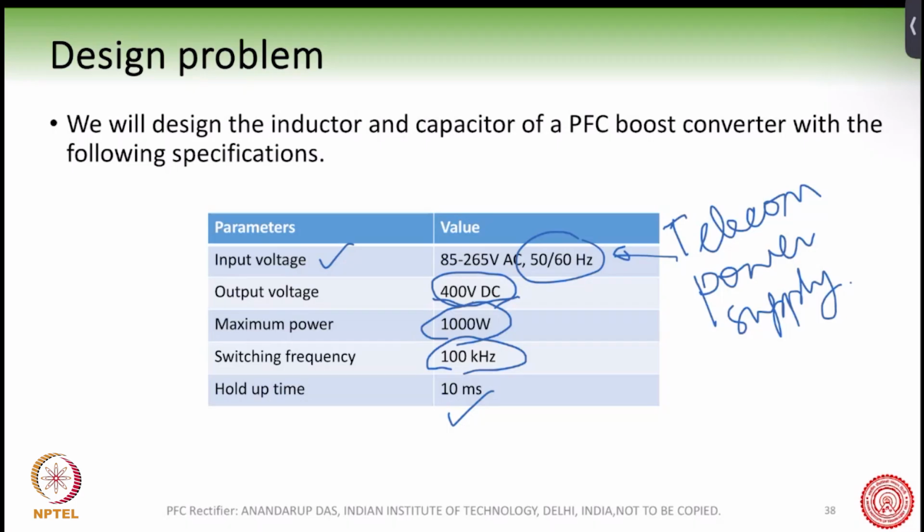But now as a power supply maker, your job will be to provide power to the load in spite of that glitch happening from the grid side. So one stringent condition is that you lose the grid for about half a cycle or one cycle, but are still able to power the load in the absence of the grid. This is done by this hold up time here.